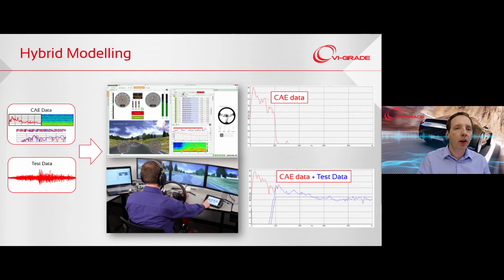For example, say road noise is being analyzed. A detailed finite element model of the vehicle and a high-quality tire model are used to generate road noise levels for the vehicle, but only up to about 200 Hz. This data can be accurately generated and played back in the NVH simulator, but listening to sound data up to 200 Hz with nothing else above that is not so realistic. A good solution is to use surrogate road and wind data from a similar vehicle, perhaps even modified slightly to match future vehicle intent, and apply this above 200 Hz, while using the detailed analysis results below 200 Hz.